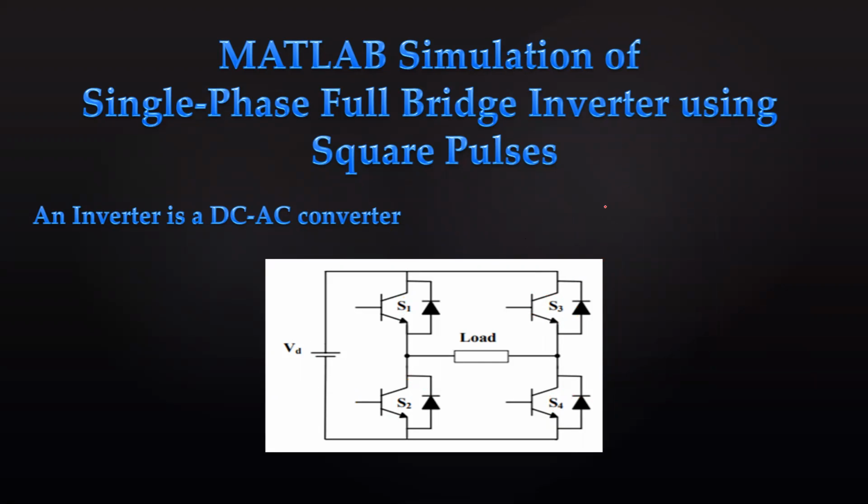We will trigger each of these semiconductor switches at 50 hertz, that is the power frequency available in India, and 50% duty cycle. If we put 50% duty cycle, then only we will get the positive and negative half cycle of our AC output equal, right?